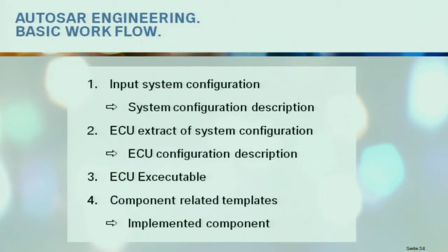So the basic workflow is you have the system configuration, meaning all the software components needed in the system together with the communication between the software components. This is the system configuration description, and together with the set of control units, you get the ECU configuration, the control unit configuration.